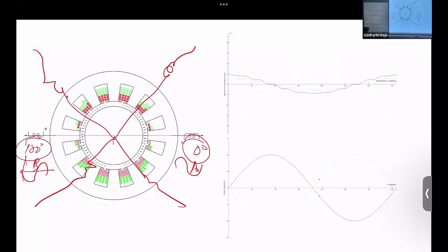So when they wind the six-phase, this is also used because you can parallel the currents coming out of an inverter leg. So you have an inverter switch rated for, let's say, 100 ampere, but your motor is going to have to run for 200 amperes. Then you can put 100 ampere on this leg, 100 ampere on this leg, basically paralleling the winding. So you get 200 amperes effectively going into the motor without stressing the inverter. So there are advantages to doing it.